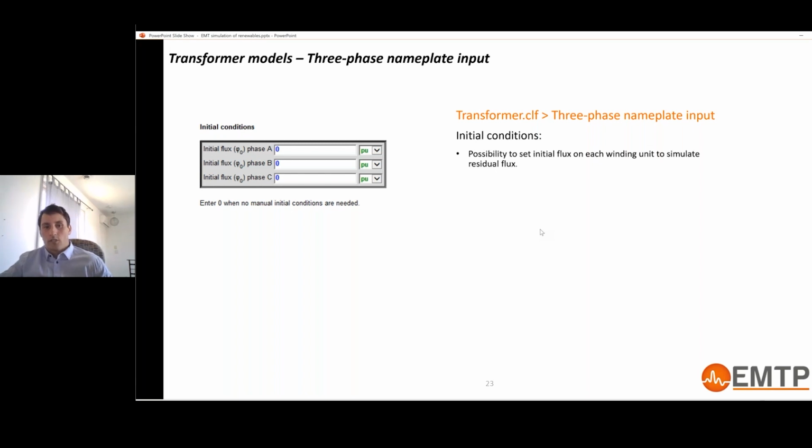And so when you do a switching study, the goal is to find out the voltage sag. You have different ways to do that. Either you simulate very precisely the de-energization of the transformer, modeling in detail hysteresis and so on, and you find out what could be the residual flux. This is a very difficult study to do because you have many unknowns.